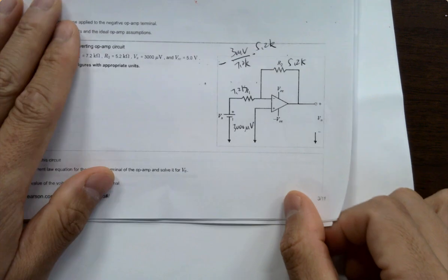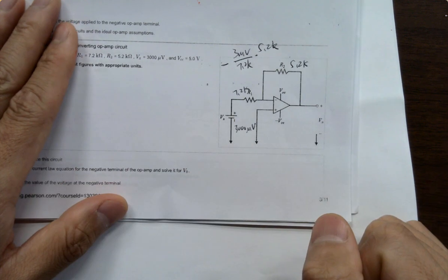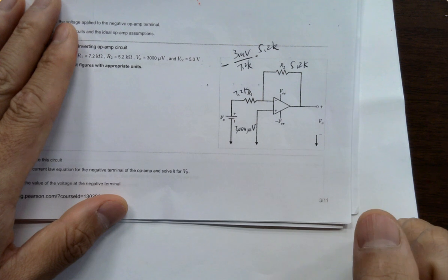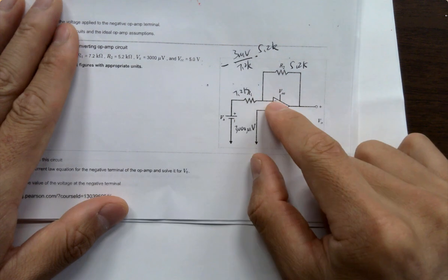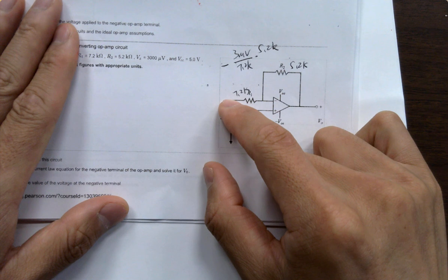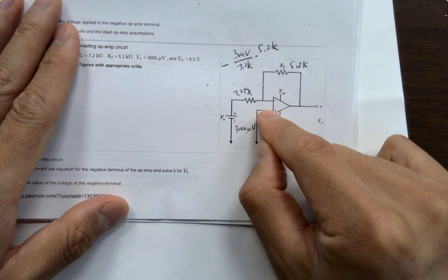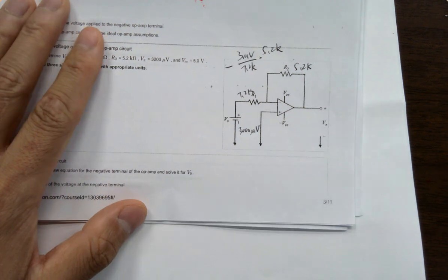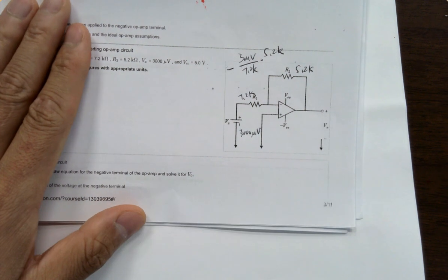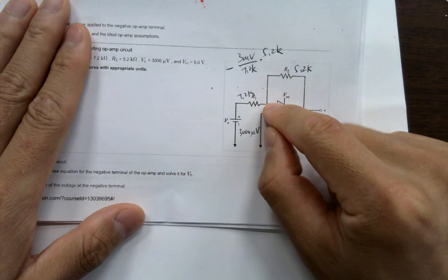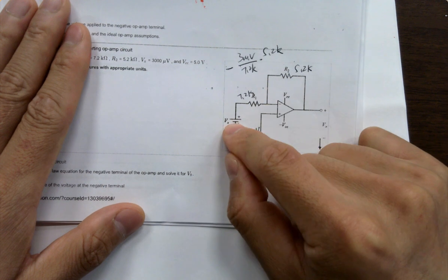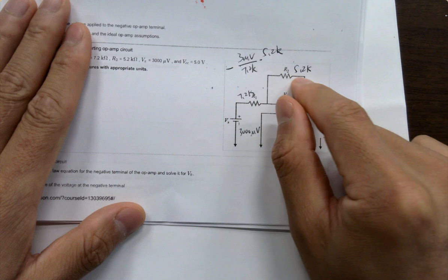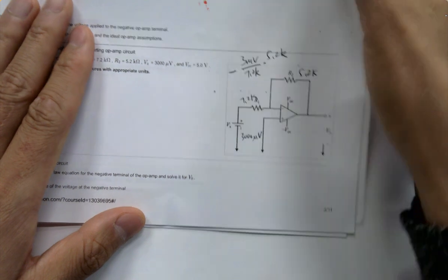So you can calculate everything here, no problem at all. What about this? That's the same problem, right? Inverting configuration, got a voltage V in, and it's grounded, 0 volts, negative feedback, and ideal op-amp assumed. So it's infinite open loop gain, 0 volts, 0 volts. You got 0 volts here, Vs is given, find a current, done.